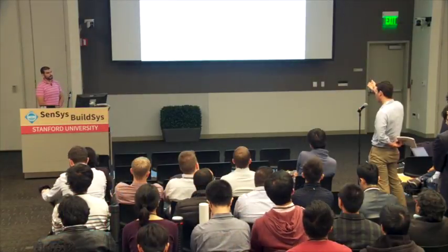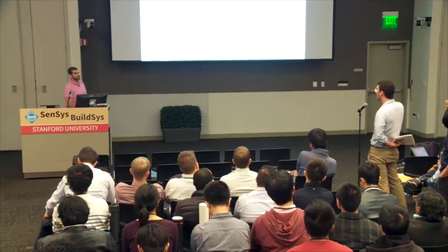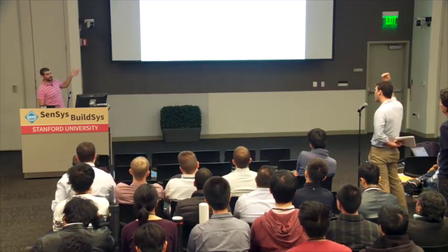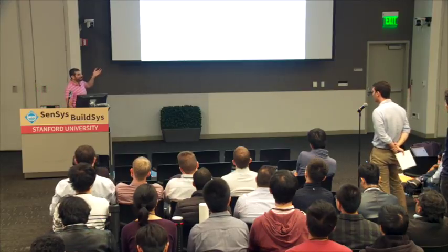And what about the other noises? Like you said, it's much smaller than the noise from the... how much smaller is it? You're saying like the flicker noise? Well, the op-amps that we used are not even very good op-amps, and yet the input referred noise is maybe a few nanovolts per root hertz, maybe a few tens of nanovolts per root hertz. But compare that to the noise from that diode input referred to the op-amp, which is like 100 millivolts per root hertz. No, that's not right, 100 microvolts per root hertz. It's much, much, much bigger. So there's some extra effect from thermal noise, but this is engineering. It's zero. Okay, thank you.